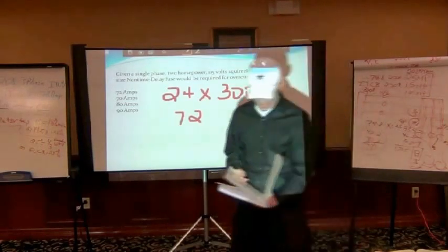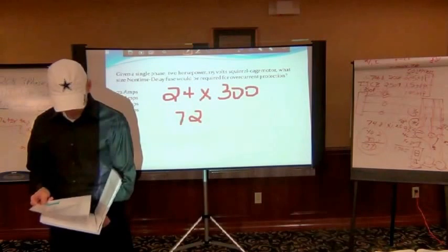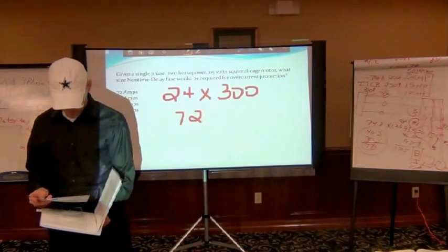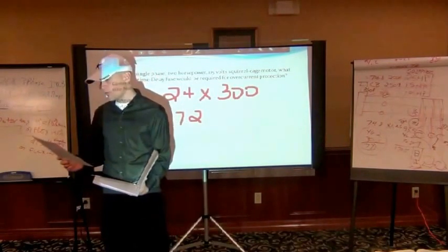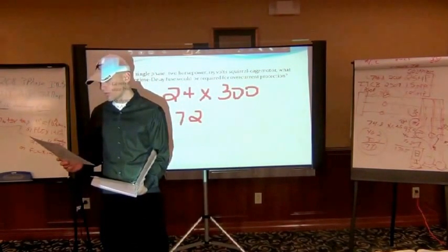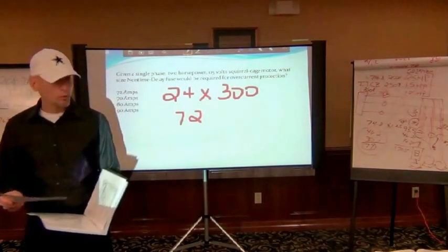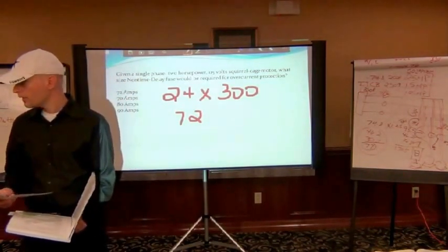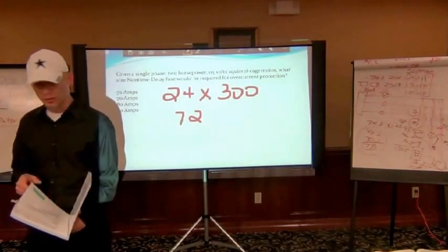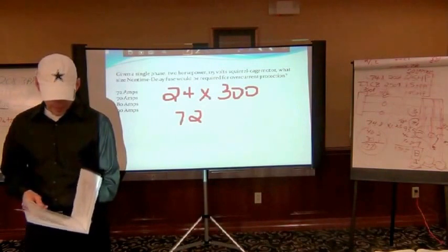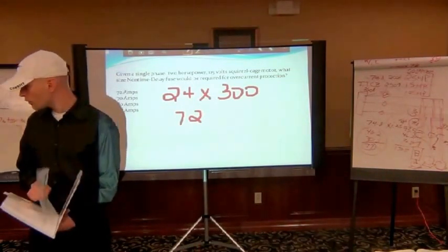All right. The questions that you had on your pre-exam, you had one motor that was a 3-phase 208 volt, 20 horsepower, had a service rating of 1.15, has no trouble starting. What size overload protection should it have? What kind of question is that? What are you sizing for? That's right, and that's under which table? What page number would you find that on? 320, beautiful.